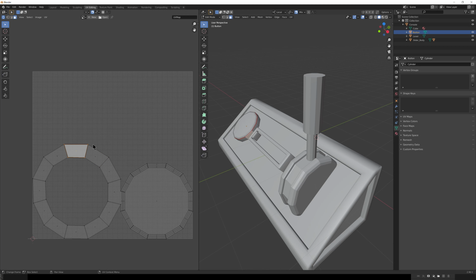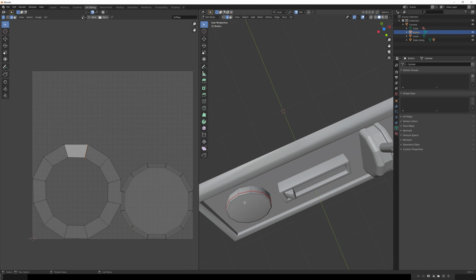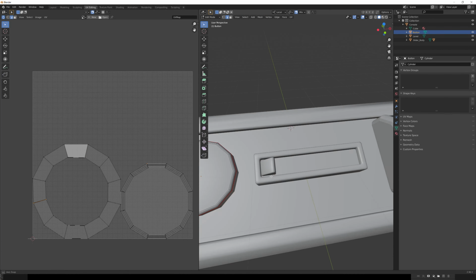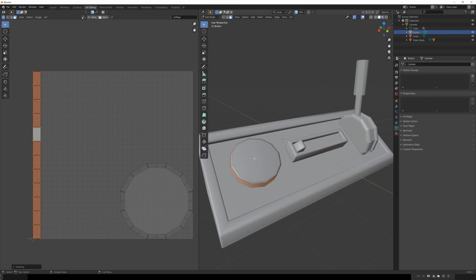So let's go ahead and choose 2. Just click somewhere, and here you're probably not going to see the top of this button right here. So if I come here, right click and make that a seam, and then we go ahead and hit 3 on the keyboard, I select one of the faces, I can use L to select the islands, or a linked pick as it's called here, to select the entire thing. We can right click and do an unwrap, and you can see now that that went from that odd circle shape to a perfectly laid out line that I can work with.